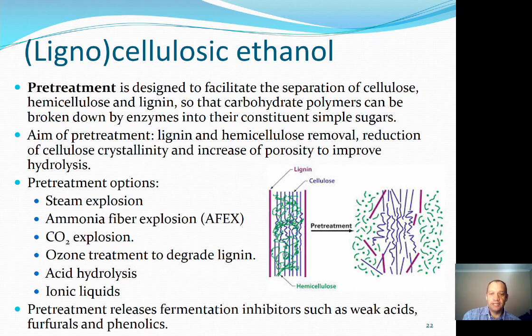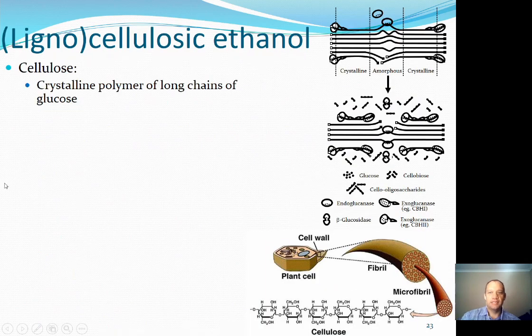And then you get phenolics that are released from the lignin. These can be quite toxic in the mix as well. But pretty much every pretreatment method that you choose will release some fermentation inhibitors. It's just inherent to the process.